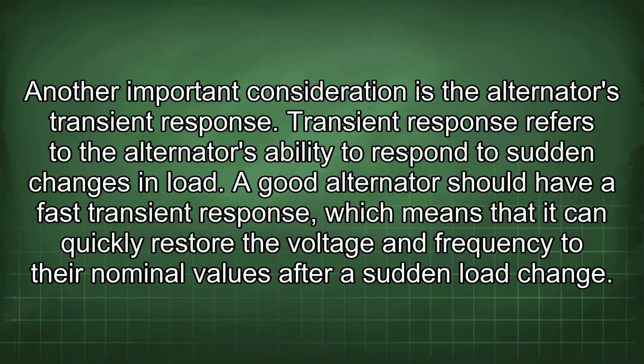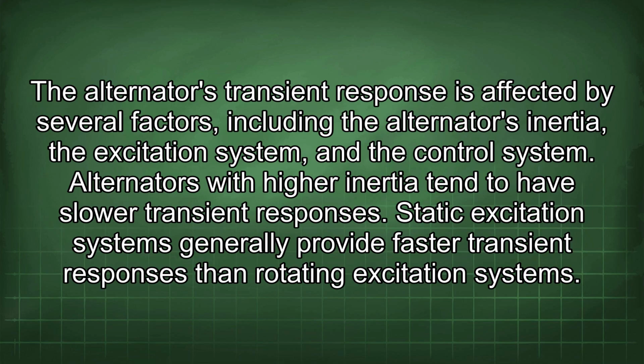Another important consideration is the alternator's transient response. Transient response refers to the alternator's ability to respond to sudden changes in load. A good alternator should have a fast transient response, which means that it can quickly restore the voltage and frequency to their nominal values after a sudden load change. The alternator's transient response is affected by several factors, including the alternator's inertia, the excitation system, and the control system.